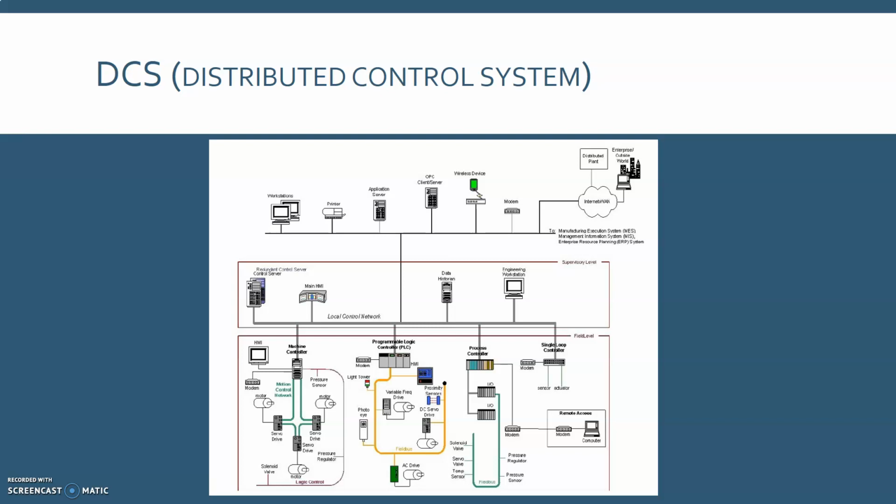This supervisor would encompass a manufacturing cell containing a machine controller that processes a part, and a robot controller that handles raw stock and final products. There could be several of these cells that manage field level controllers under the main DCS supervisory control loop. So this is what we have for a DCS, that is a distributed control system.